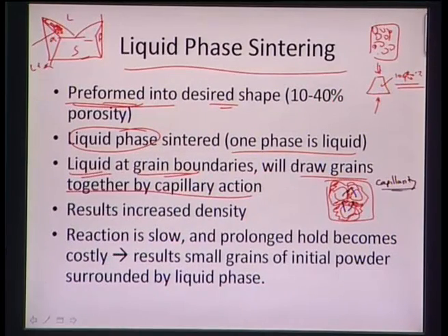So because of capillarity, everything will tend to come closer and get consolidated, and it will lead to increased density in the structure. So this is what is happening here: it leads to increased density because of the capillary action, because liquid is present at the grain boundaries, which will tend to draw all the grains together, and that will make the structure highly dense.